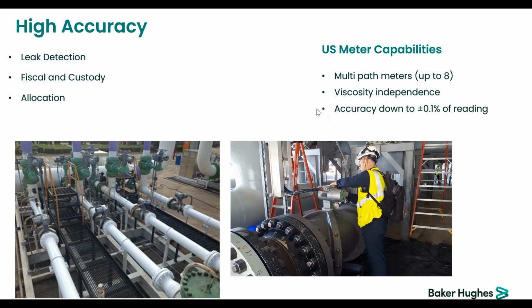If you have a process meter, and if you have the diagnostics that are staying within the permissible limits, there's a high threshold and a low threshold. So if they stay within these permissible limits, it is not required to do anything around calibration. If you have the velocity of sound that stays within the expected range of the theoretical value of the speed of sound, there's no need.